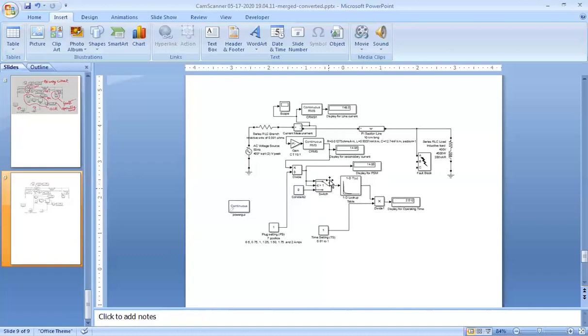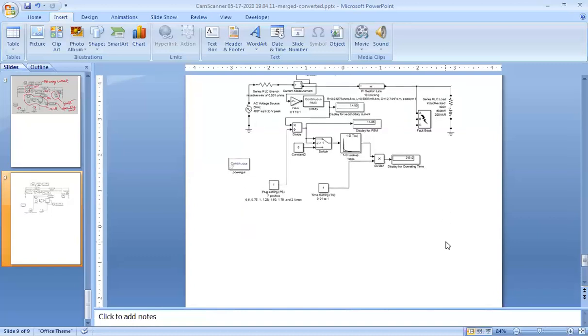And if the PSM is not greater than 1, that is, less than 1, then it will take the value of 0. So for 0 PSM, the time taken will be very, very high. It may be say 70, 80 or more. So in that case, if the value appears to be 70, 76, 80 like that for 100% time setting, you just avoid it. You can assume that the relay is not operating. Okay. So that's all.